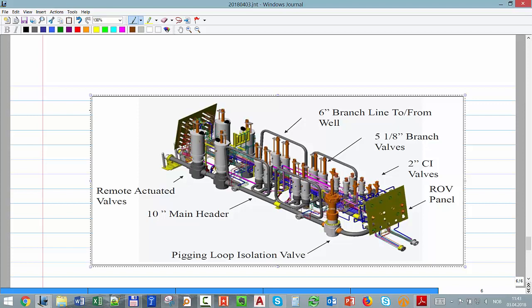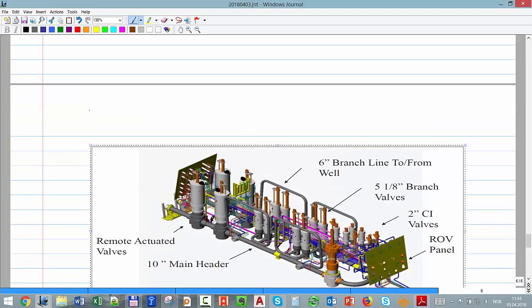Let's say that we are producing through that header. If that valve, a crossover valve, is closed, then in all of this piece of pipe from here to here there will be no flow. So the fluid in this region will cool down, and then you might have problems with hydrate, wax, or all kinds of issues here. So we analyze all of those, what we call dead legs, to see where my dead legs are in my system and what problems they may have.